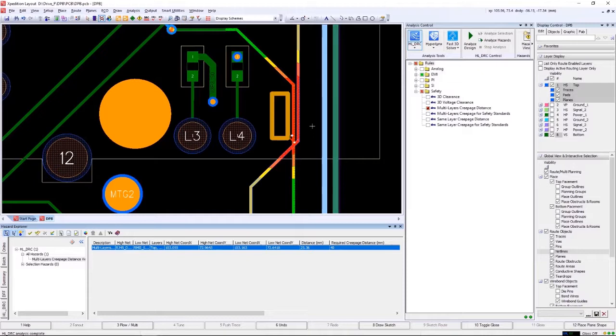And we can see using this multi-layer rule, we have a high voltage aggressor net on the top side of the board on layer 1 that is going through this contour or hole in the board, this cutout we made, and going down into the bottom side of the board and affecting our victim net on the bottom side of the board.